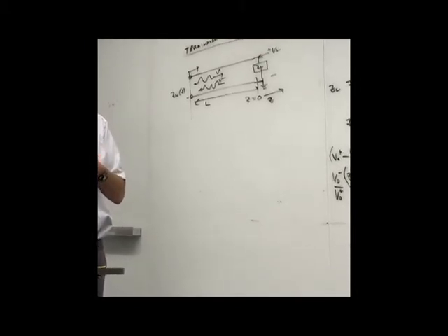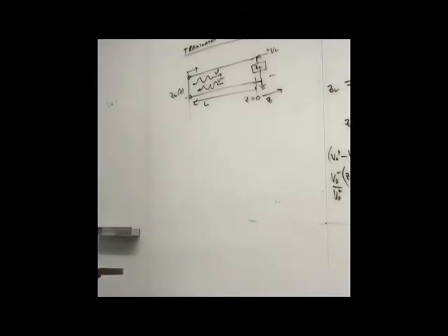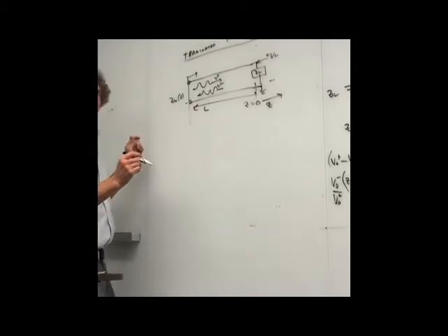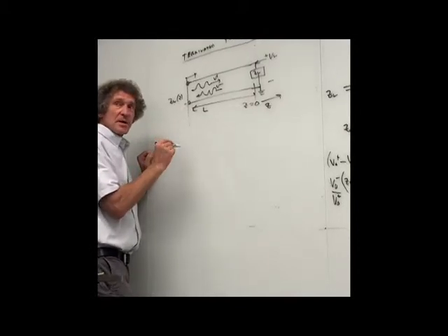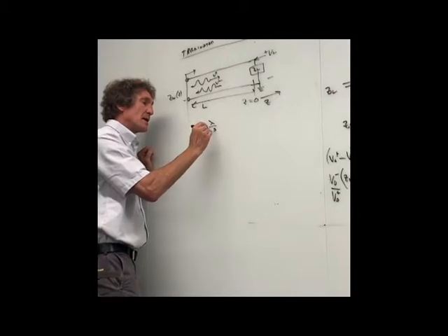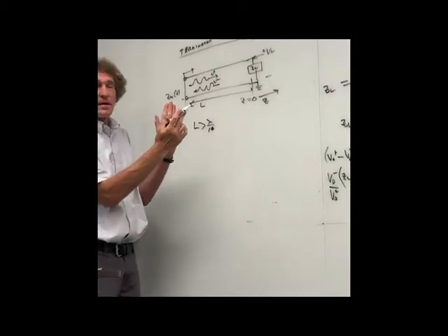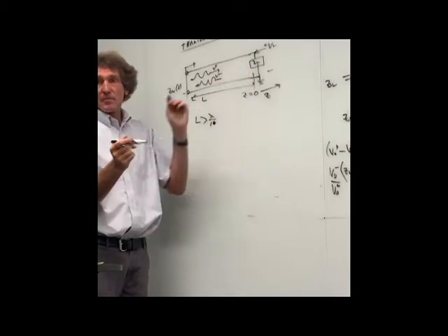That's a reasonable thing to ask. You would love to know that. We want to see how much it fluctuates. And I've got to say one other thing about this too. For this to act as a transmission line, remember, L has to be greater than lambda over 10. If it's less than lambda over 10, these wires are basically short circuits, and your impedance is just ZL.